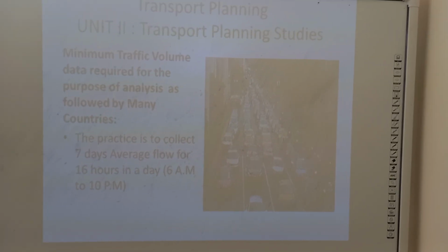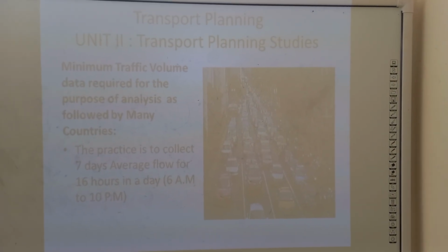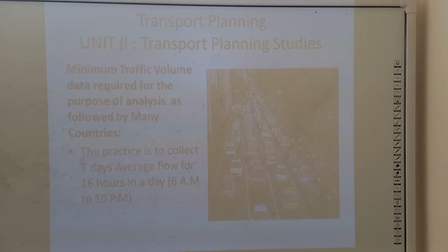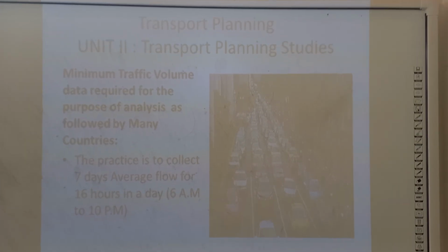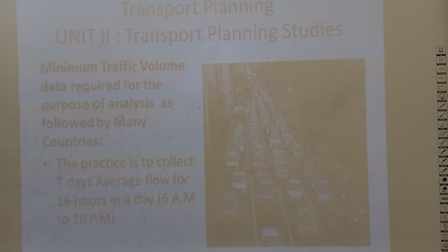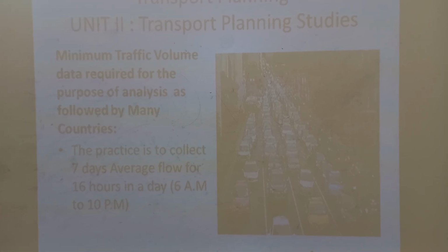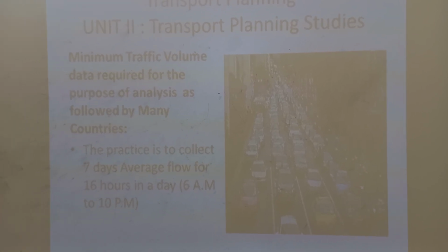This volume will be useful for different purposes. Volume can be used to put forward different management measures on the road. It can be used to recommend new infrastructure on the road. It can be useful for pedestrian facilities also. It can be used for signal design. It can be used for signal synchronization. So for so many aspects we can use it.